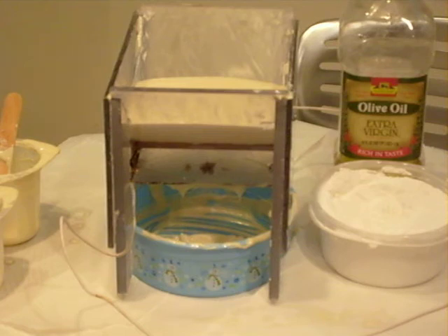You also have to worry about the particular electrode configuration. We chose two parallel plates in our valve in order to achieve our electric field. Some of these reasons are why MR fluids have much more application in industry and manufacturing than ER fluids.